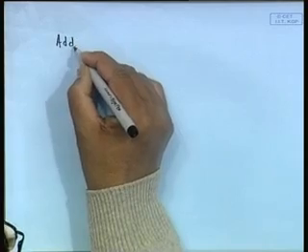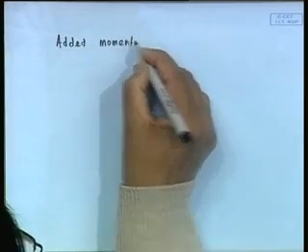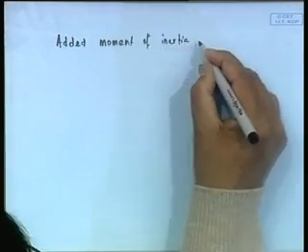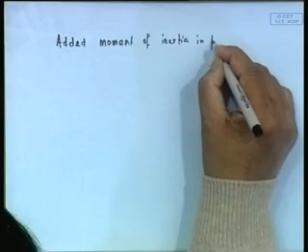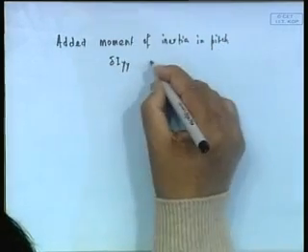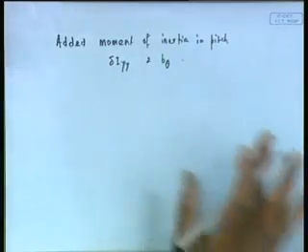Okay, we will continue our talk on this uncoupled pitch and heave motions. Let me look at this estimate for added moment of inertia in pitch and also the damping, that is basically del Iyy and b theta.